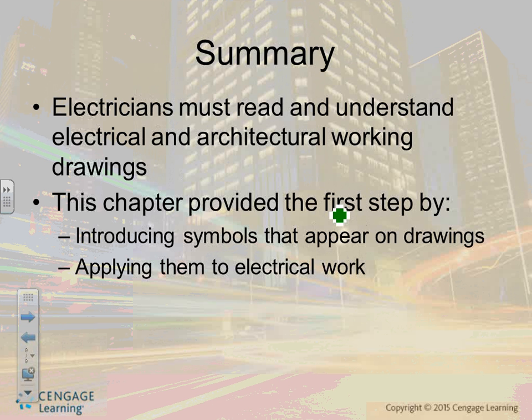Can you put a 40 amp fuse in a 100 amp disconnect? No. The disconnect must match the fuse or be bigger, because you have to fit the fuse in the disconnect, so it has to be at least the same size. Anyway, there's thermostat, relay, all this good stuff. You guys read through them. Limit switches, LS, and so forth.